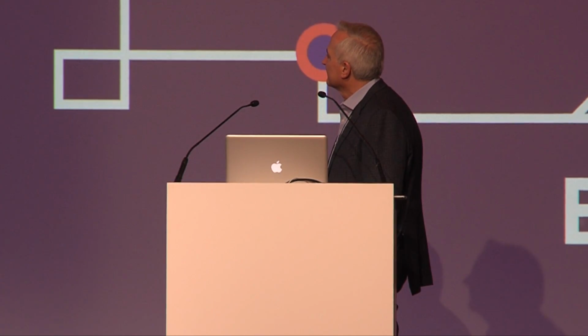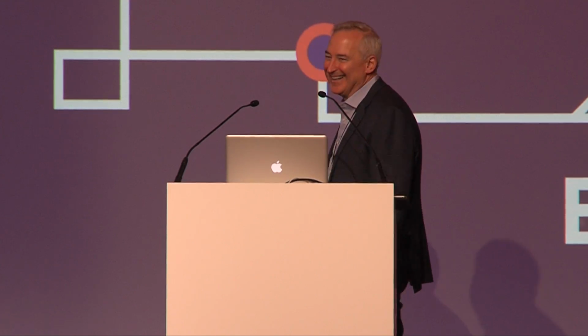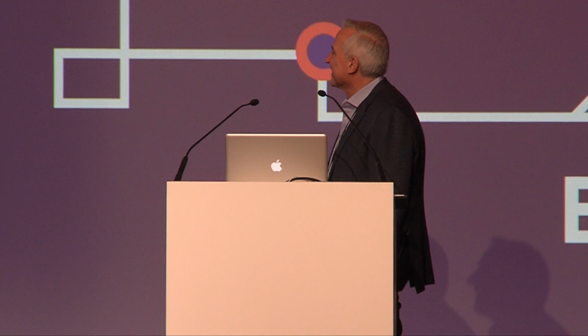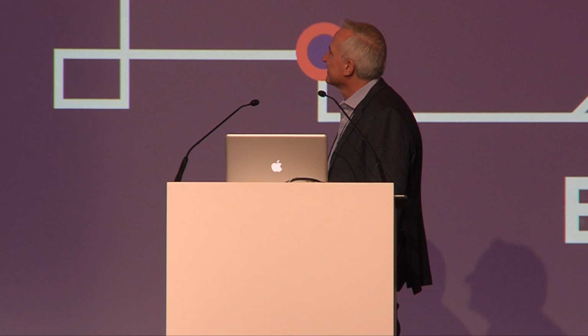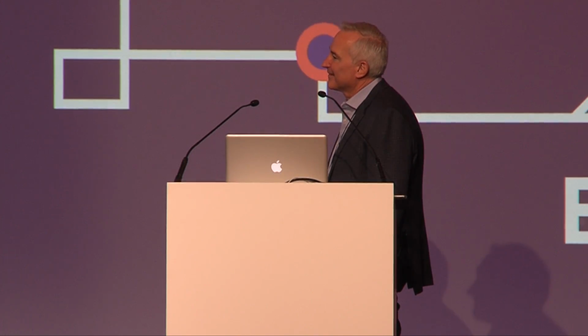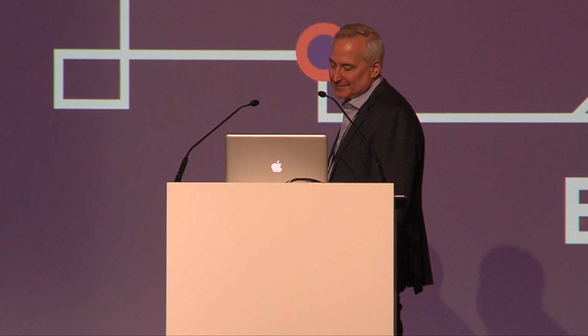So yeah, we'll go through that. Nothing unusual up to here. Also at 1,200 meters. And then suddenly 10 million kilometers, this arc. That looks wrong. So it's out there in space. So I will just erase it. And let's see what happens now if we do zoom extents again. It's cured, the drawing. So you can use this tool. It's incredibly easy to modify how you want to look at your drawing today.